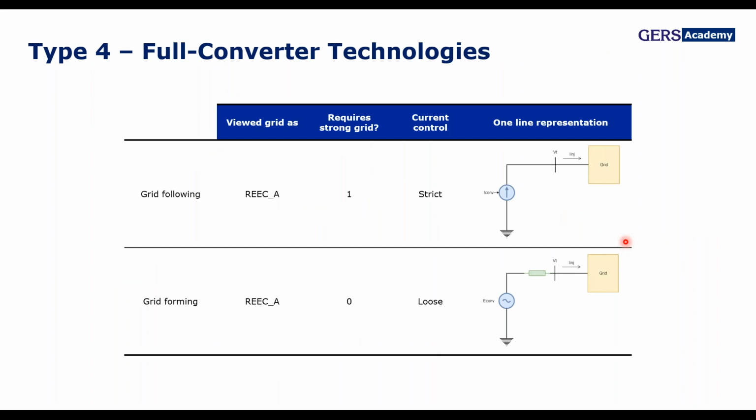There are two types of technologies for the inverters nowadays, grid following and grid forming inverters. Most of the technologies for these huge PV plants or wind turbine plants are grid following. What it means is that they depend on the power system. They just follow the signals from voltage and frequency in order to interconnect to the system.